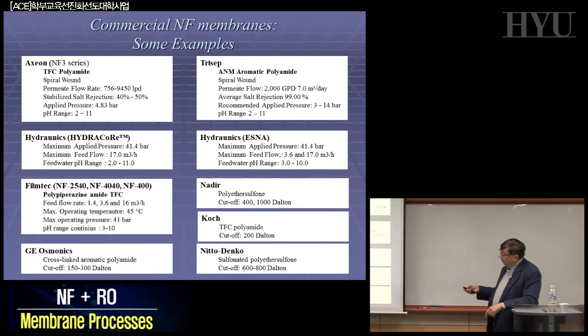If you want to recognize nanofiltration, except for the symbols, you will see that, for example, salt rejection here is no more very high, because normally in this kind of system, first of all, the applied pressure that is necessary is much lower than the one we will use in reverse osmosis, but higher than the one you normally use in ultrafiltration. Ultrafiltration is normally 1 or 2, 3 atmospheres. Here you can have 5, 6, sometimes you can have 7, 10. But the selectivity is relatively low.